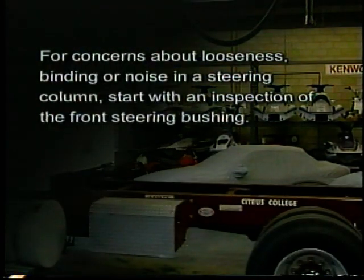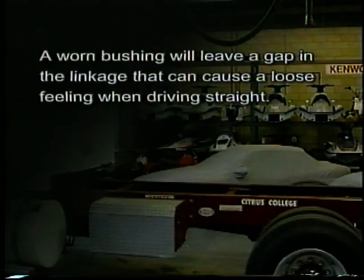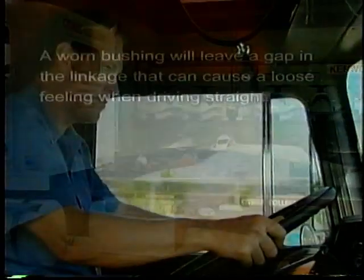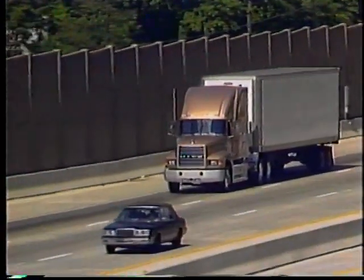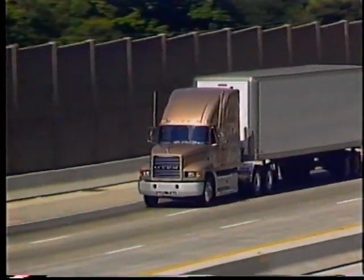For concerns about looseness, binding, or noise in a steering column, start with an inspection of the front steering bushing. A worn bushing will leave a gap in the linkage that can cause a loose feeling when driving straight, or a noise over bumps, or a pull to one side as the vehicle drifts on the crown of the highway.